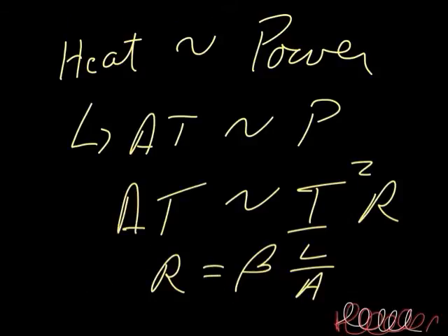I'm going to put power into this thing, and the power that I'm using up within the thermal actuator is proportional to the change in the temperature, and the change in the temperature results in lengthening of that beam. And we can change that delta T by changing R. So if we can make this resistance bigger, we can get a bigger effect on the change in temperature. Does that make sense?